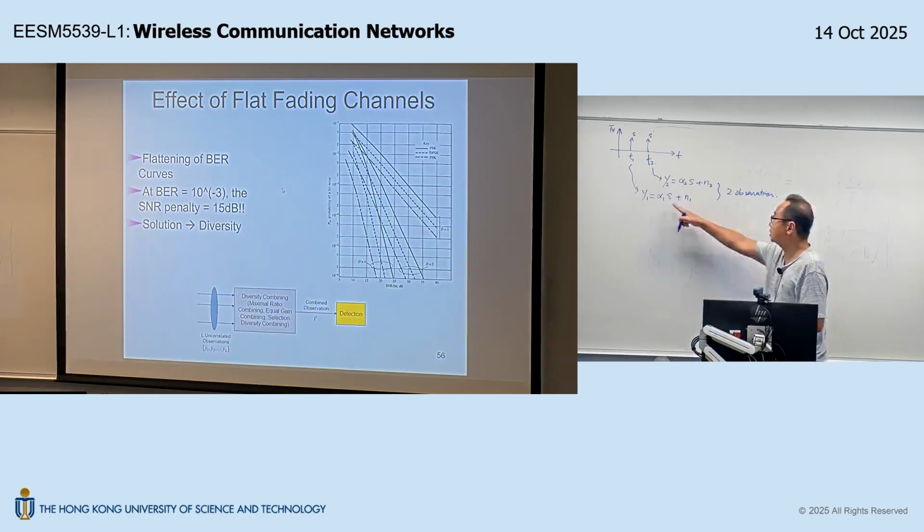If they are correlated, that means if this one suffers from deep fade, just like when you apply to the first company, if the first company is not so favorable, and the second company is heavily correlated, then the second company may likely reject your application as well, right? So how do we make sure that alpha 1 and alpha 2 are independent? Even if this is in deep fade, it doesn't affect the chance that the other is in deep fade or in good shape, right?